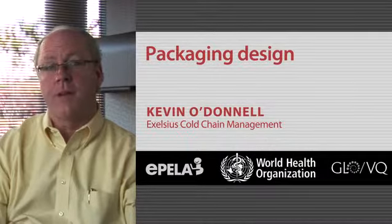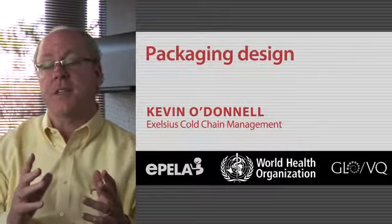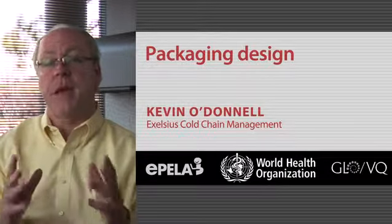Now we can take these three concepts of heat transfer and apply them to package design. For instance, in our insulated packaging system, the insulation acts as a thermal resistor, blocking the transfer of heat. The more that we can block that heat, the better off we're going to be in the long run, because our product is going to be better insulated and better protected. Now the refrigerants that we use inside the package to help keep the product cool actually act as a thermal capacitor. It stores and releases heat energy.